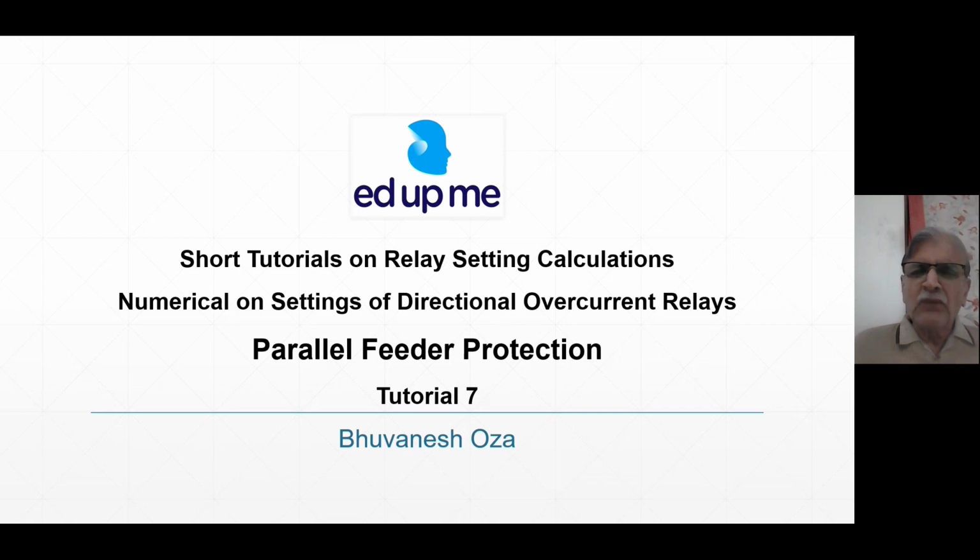I hope everybody knows that parallel feeders are quite common in the field practices. The rows of towers is there. So on left side there will be RYB one feeder, on right side RYB second feeder. If on one feeder you can transmit 100 megawatt, then on two feeders you can transmit 200 megawatts from one point to the other, from one CT to another. That means double the power can be transmitted without any extra cost of transmission towers. No doubt, cost of insulators and conductor is added, but tower cost is saved. That is why the parallel feeders are very common.